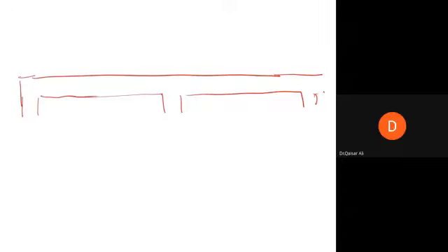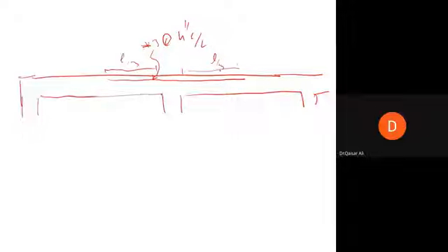And so on. So a negative reinforcement we placed here. This is number 5 at the rate of 4 inch center to center. And this will be extended up to L by 3 on both sides. The spacing is different in the negative reinforcement.